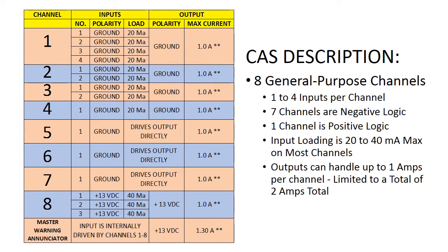In terms of inputs and outputs that can go to this circuit, typical inputs could be chip detector, the clutch switch, temperature and pressure switches, various kinds of modules, battery low voltage warning module, a rotor RPM alarm, engine RPM alarms, and all of the various UMA custom Helicycle instruments that I sell.